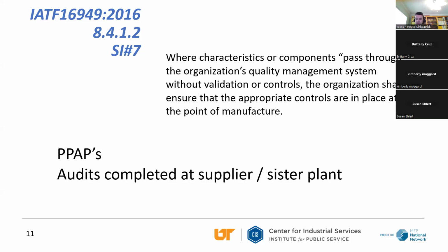Anybody else have any other ways they've done that at your organization? We've done poka-yokes before for presence or lack thereof. What was that, Bill? Poka-yokes. Okay. We'll put in a pin or something, a breadboard, just to make sure that the feature's present. So if someone does screw up, we're not going to compound it at our customer. Okay, so you're doing some kind of an inspection or additional check to it. Okay.